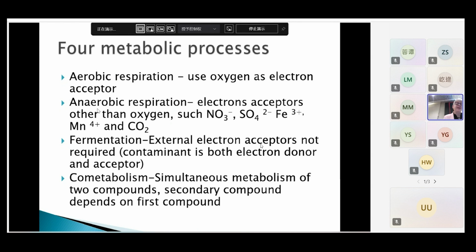You need to have a good temperature range. Bacteria can work at almost any temperature, but ideally the 20 to 30 range is probably the best to work at. During the summer, if it's too hot, sometimes they don't like it. Basically, this range of maybe 15 to 30 is probably the most optimal. So you just have to try to get in the right range.